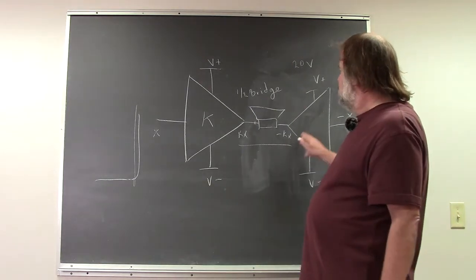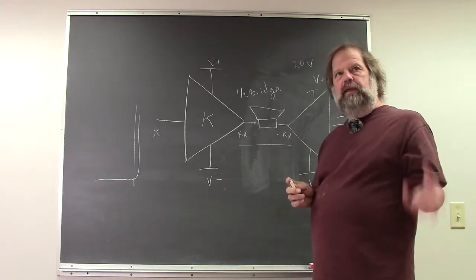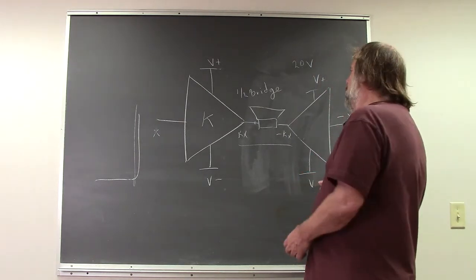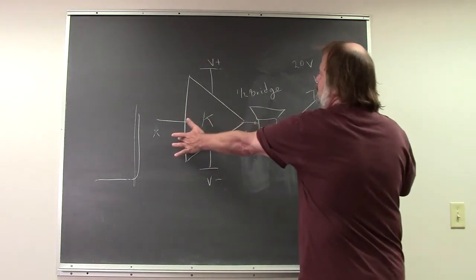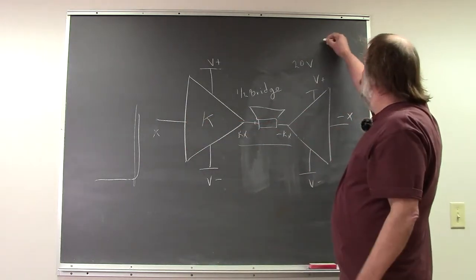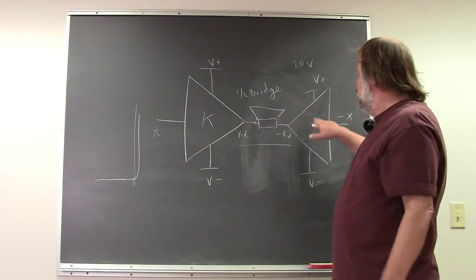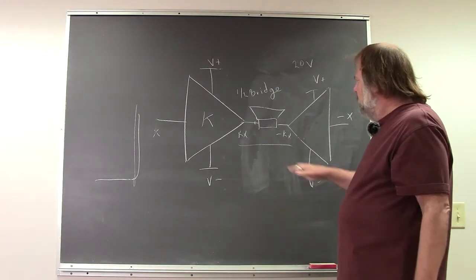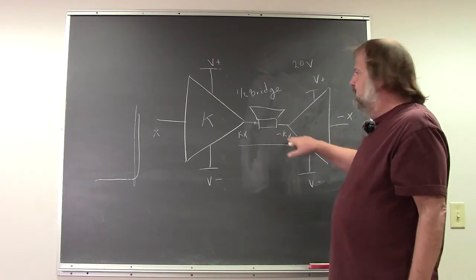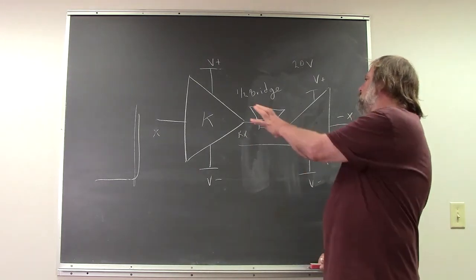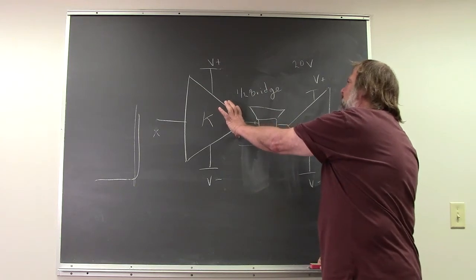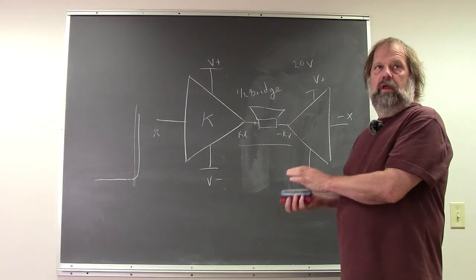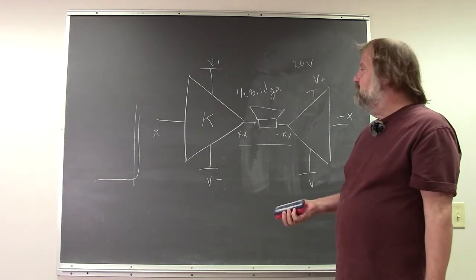And what that's going to do is give me 6 dB more output, or 6 dB more signal to noise. System-wise, it's going to quadruple the power because the voltage is squared, or in individual amplifiers, each one's double in its power requirement. But that's one way of getting twice the voltage swing. If the amplifier is already supplied as a full bridge, in other words, this and this is built internally, you can't do this. And some amplifiers are built this way intentionally, so you need to know that.